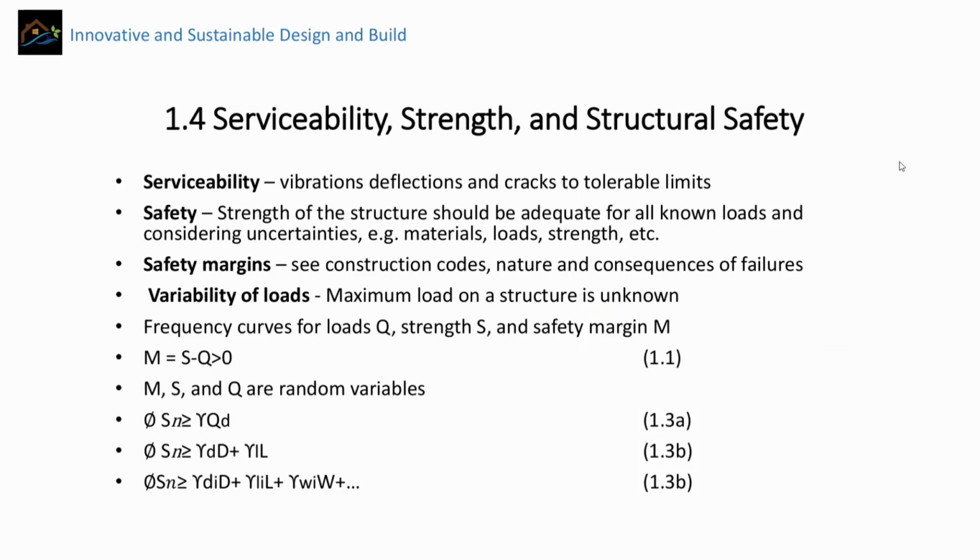So it has to be safe enough to withstand all the loads. It has to have quite high strength compared to the calculated loads, and it also needs to be serviceable. Serviceable means that the building should not be subjected to cracks beyond tolerable limits.